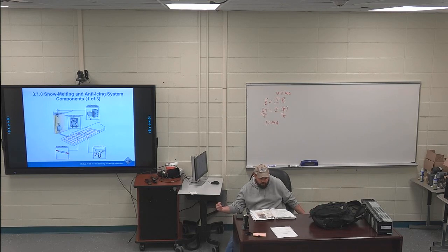In this heat cable stuff, your 3 feet of additional cable should be allowed for making power connections. 1 foot for a splice and then 1.5 feet for each connection. But key in on the 3 feet for making power connections.